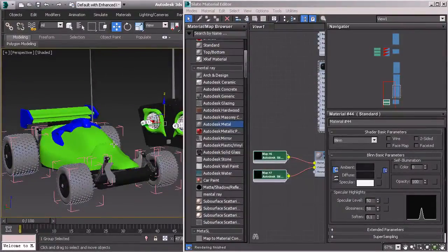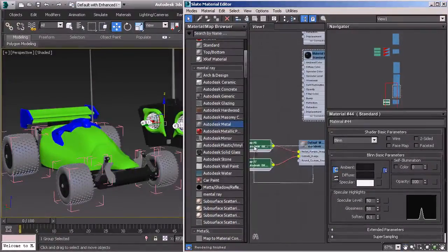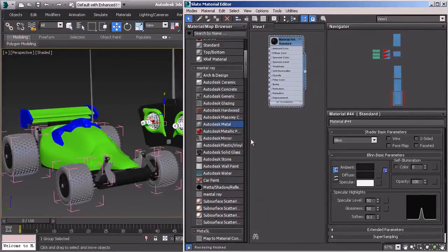And you'll get a warning saying that the material requires objects to be UV'd, and it's going to show you a list of the objects that are not UV'd that these materials are applied to, and you'll have to UV those for this to appear properly. So you want to be careful with which materials you're using. If they have maps applied, they probably will not show up properly.